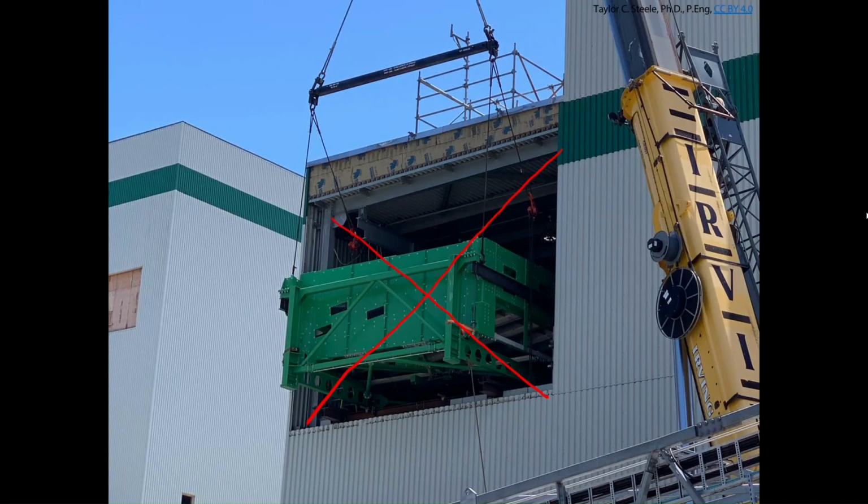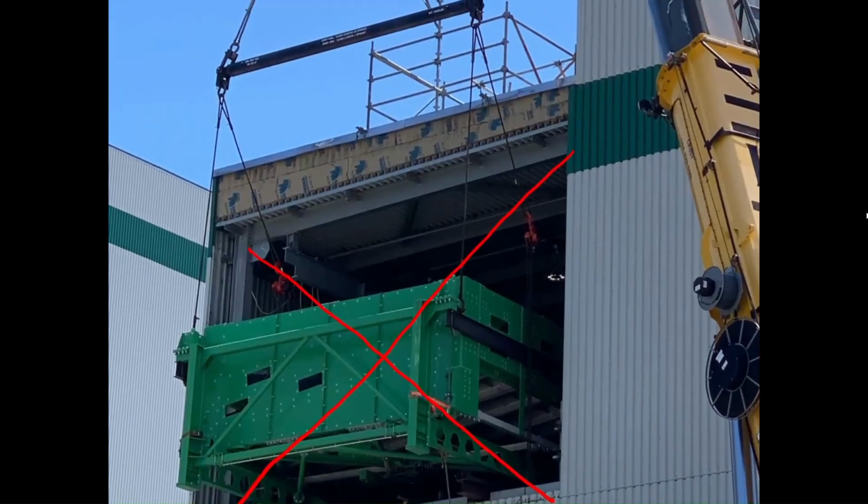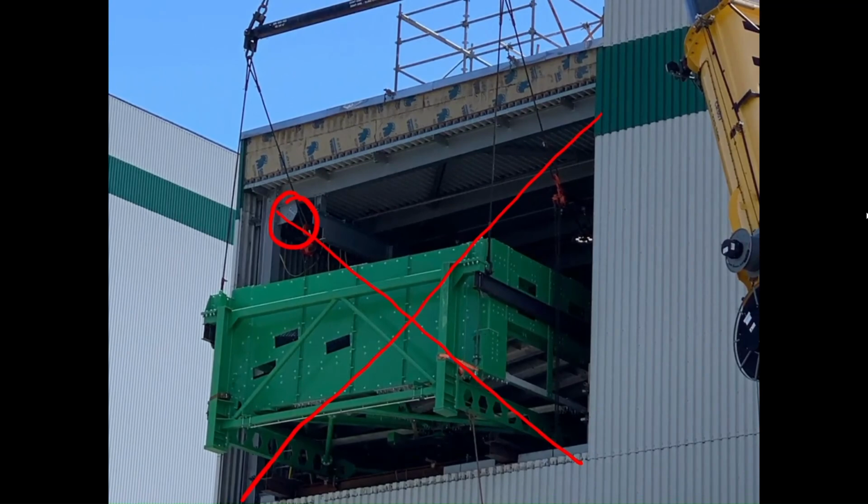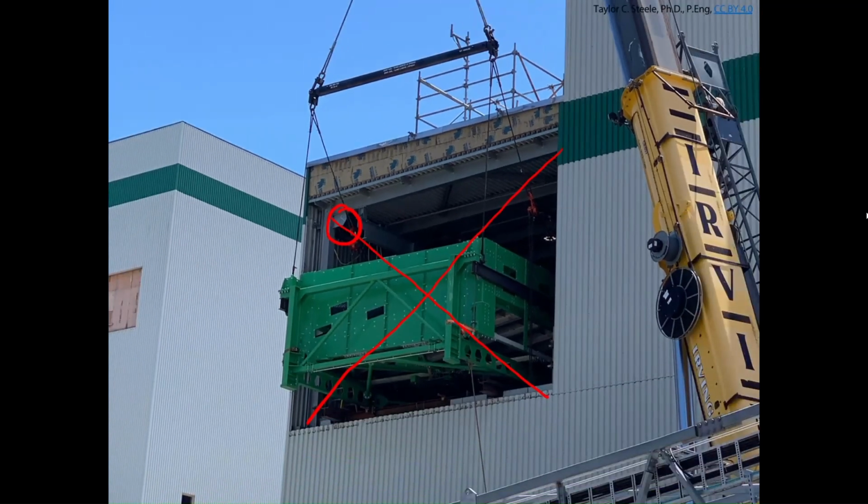We talked in lab the other day when we were playing with the MOLA kit. With bracing on at least 3 sides of the building, you can maintain stability, and you don't expect a 1 in 50-year windstorm during a 7-day maintenance. Generally, you can make that work. And the only reason they could make that work was, you can see here, they've got some bolt holes. They basically pop the bolts out in place and then put the bracing back into position, saving them a lot of time and a lot of money during a maintenance shutdown. Okay, does anyone have any questions about why we might prefer bolts or welds before we continue on?